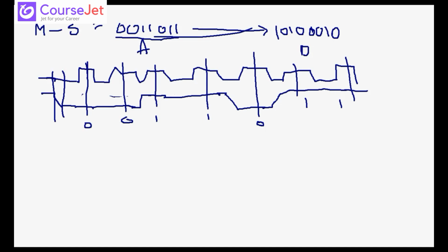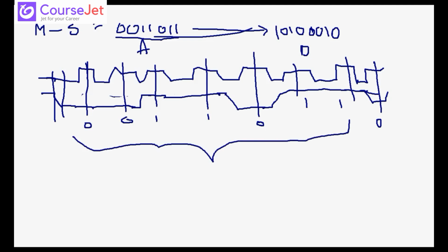Right. Now next what we are sending is your read or write bit, whether we want to read the data or write the data. So we know that we are writing data. So for writing we need to send bit 0. When your clock is high, again the same thing, give a bit as 0. So after sending this particular 7-bit address, you need to send the 8th bit, whether you want to write or read.